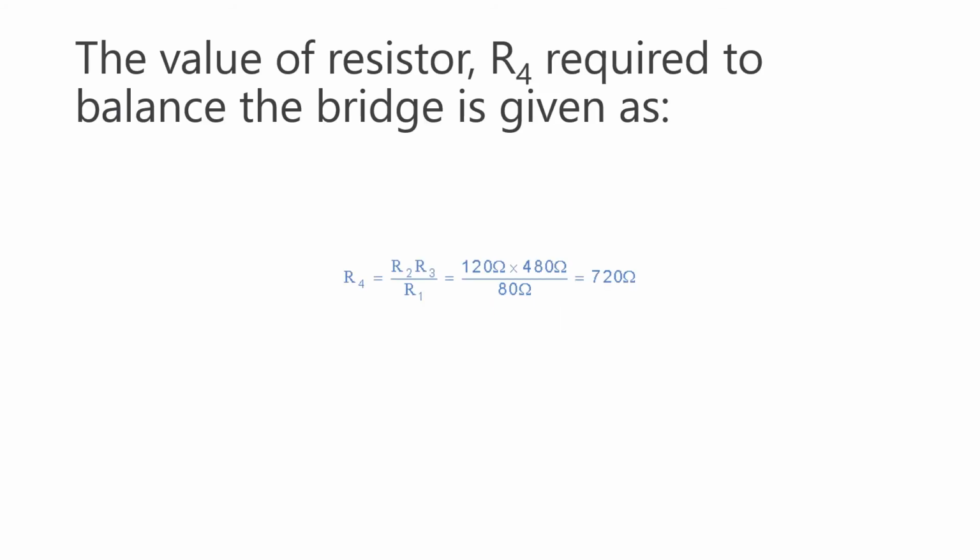So to sum up, bridge circuits are extensively used for measuring the component values of R, L and C. These bridges are also used for measurement of frequency, phase and temperature. A bridge circuit consists of four arms, maybe a capacitance, resistance or impedance, forming a closed circuit with a DC or AC source of excitation.